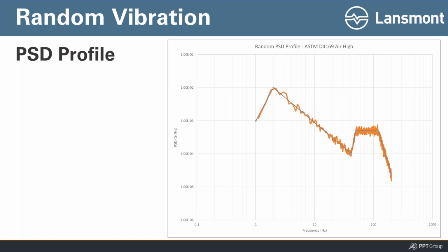But basically then, if you connect those dots together, that's what you see on a vibration controller when you're watching it run in real time. And it moves, right? Or I mean, it kind of jiggles around. The line basically stays on top of that gray line. In this example, the orange line stays basically on that gray line, but it dances. At each of those frequencies, it dances a little bit above, a little bit below. But again, remember, it's because it's changing. It's a random input, sometimes a little bit high, sometimes a little bit low, but always on average doing what that gray line is.